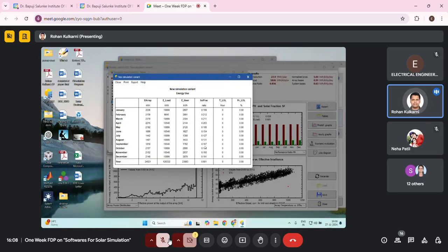So if you go for the higher software or a particular one, you need to get the data for that particular location, and you can check what is the change in the output also. So one can study with PVsyst that if I set up the plant in 1990 and 2024, what is the difference in the output based on the weather parameter changes.